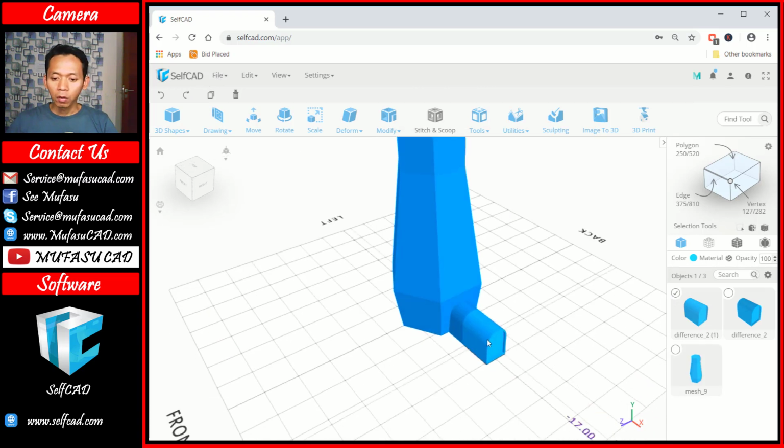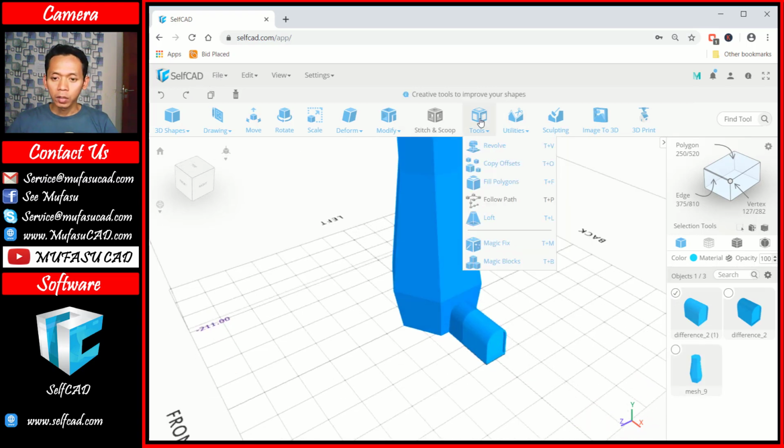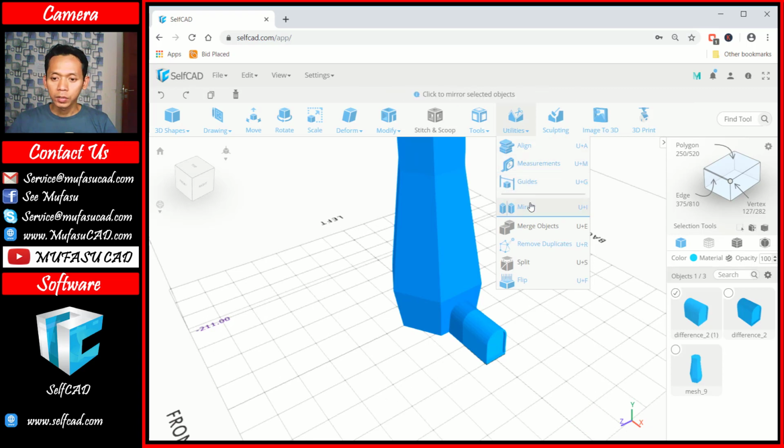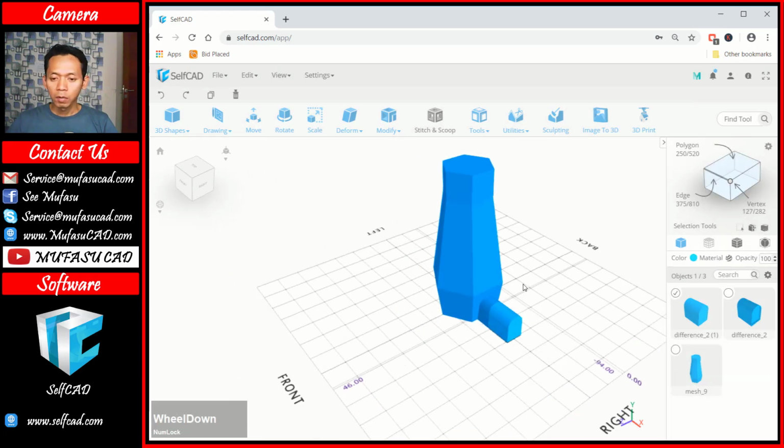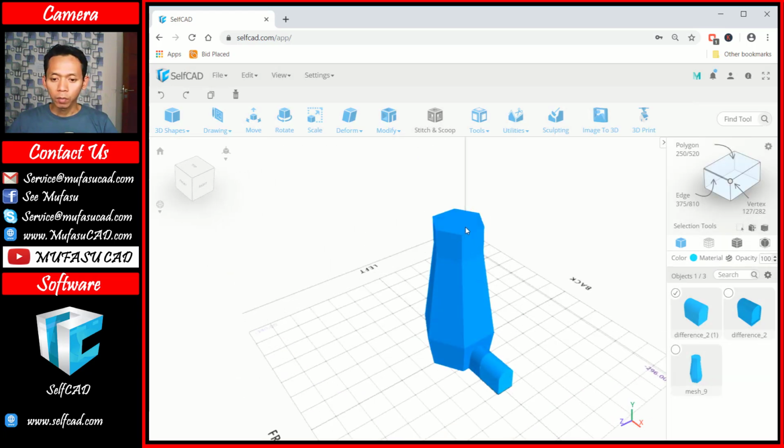Now I will mirror these 3D models. You can click Utilities, Mirror. We mirror in back and front. Okay, you can click in here. Sorry, we mirror in left and right. Okay, to this point, and click apply. Next, I will move this object to the top point here.